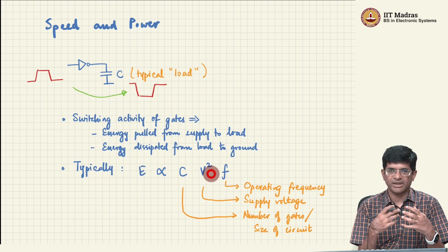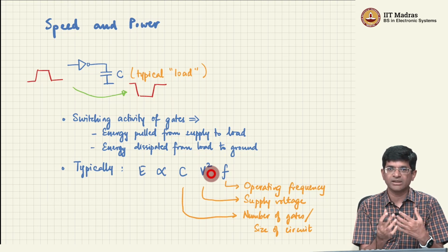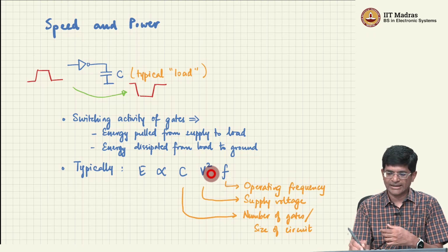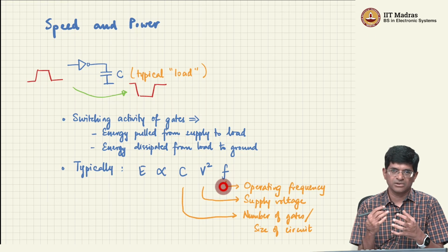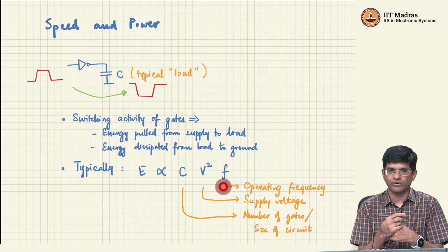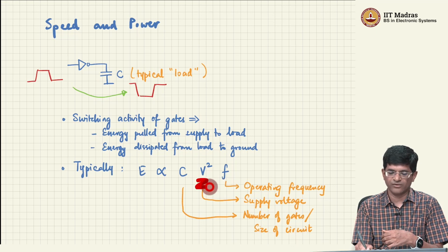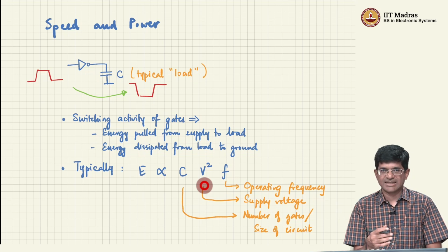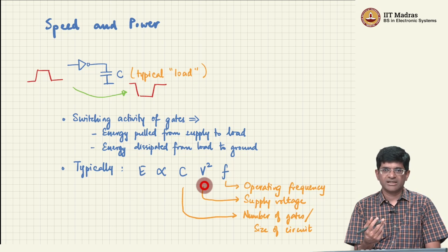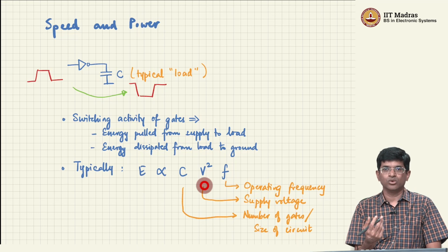It means that my transistors can no longer deliver current fast enough, they can't switch fast enough, and that in turn brings down the frequency at which I can operate. It ends up slowing the whole system down very dramatically, and I most likely won't be able to perform my computations on time if I reduce V too much. Okay, so these are some aspects that will keep coming up at various points when we talk about what we can do to reduce the power consumption in a circuit.